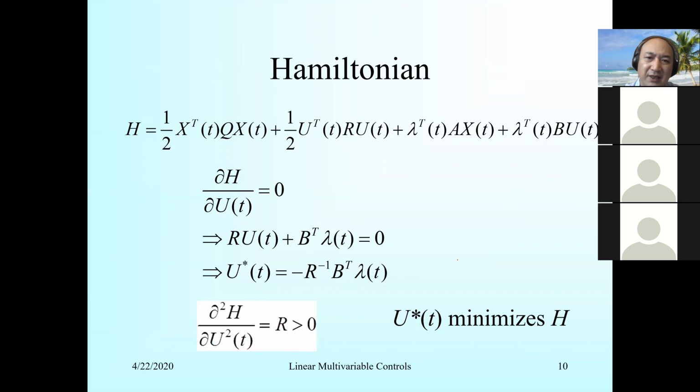So in our case, for LQR and an LTI system, we put f as Ax plus Bu, and my capital F, the Lagrangian, is half of x transpose Qx plus u transpose Ru.